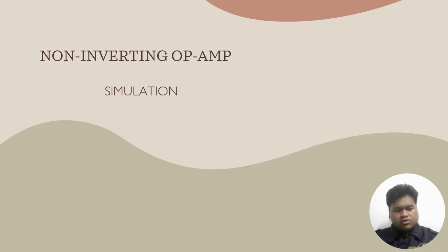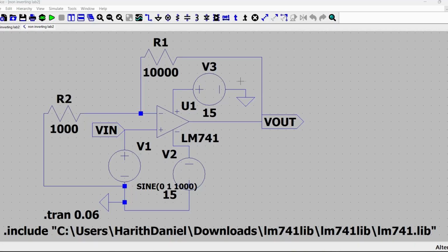So next, we will proceed with the non-inverting operational amplifier. So this is a non-inverting operational amplifier circuit. It consists of an LM741 connected to Vin of 1 VPP at 1 kHz frequency to the non-inverting terminal, and the inverting terminal is connected to a 1 kilo ohm resistor and ground, and the output terminal is connected to a feedback 10 kilo ohm resistor.